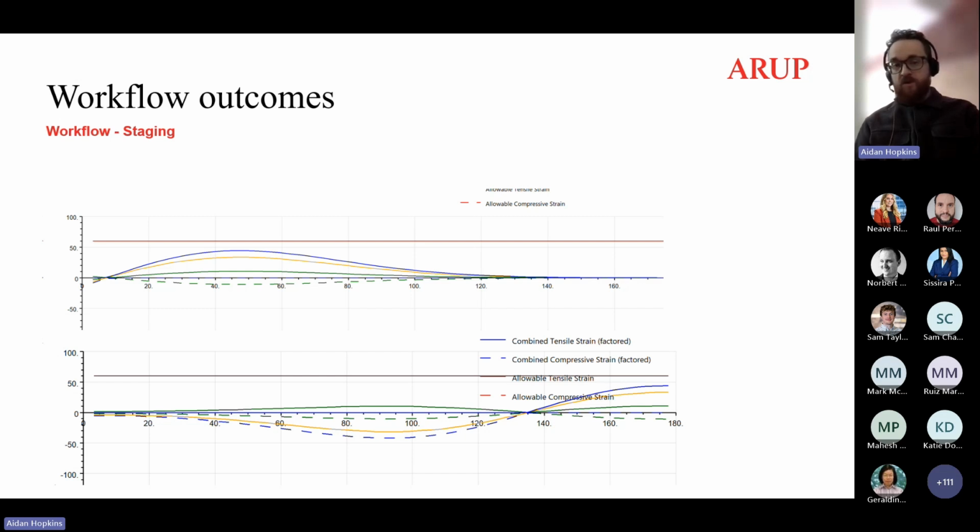And understanding that was very important because we were looking at monitoring pipes over a certain length when we exceeded a certain percentage of their thresholds, and doing this allowed us to say, okay, monitoring of this pipe needs to start at 20 meters and end at 80 meters, rather than monitoring the whole length of the pipe even as we extend out of the zone of influence.